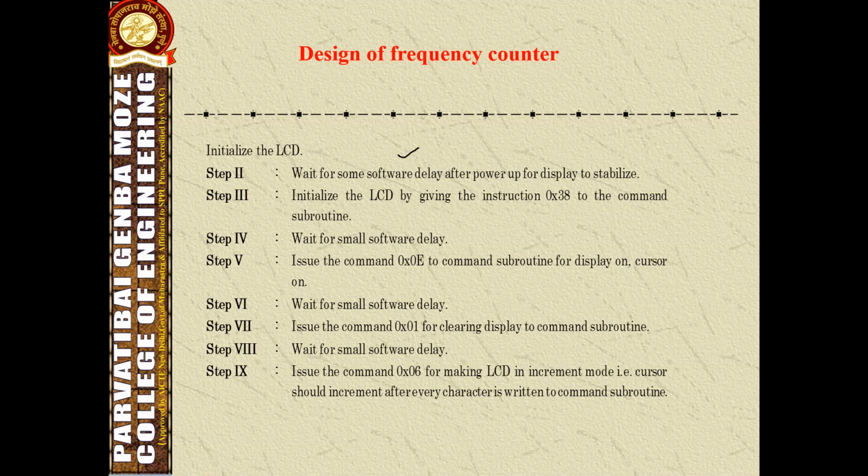After power up and initializing the LCD display, the display should stabilize. So for that, we have to give some delay, and we provide that delay by using software, hence it is called a software delay.